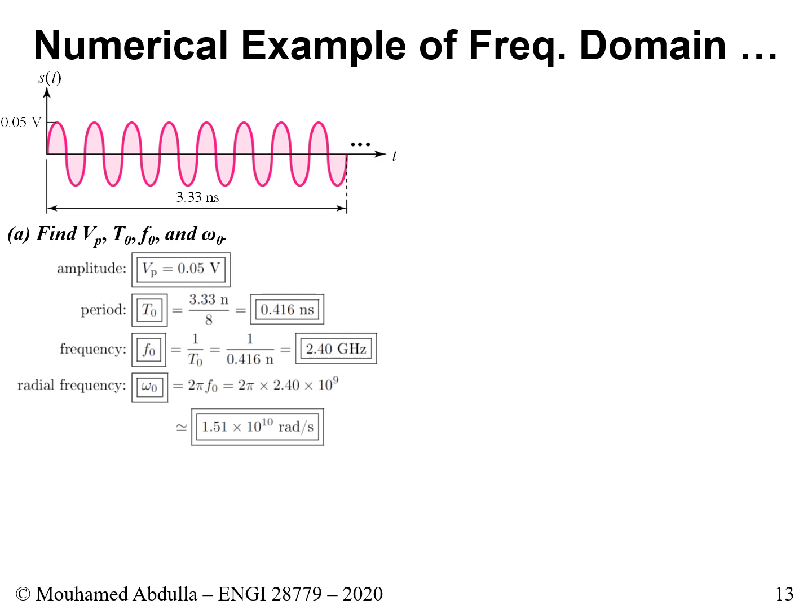This is what we get, okay? So as we said, the peak voltage is 0.05. It's here. It's also minus 0.05. The period is this entire thing, 3.33 nano. Nano is 10 to the minus 9. I hope you know your engineering notation. This is back to electrical fundamentals. You've probably taken this course with me the first semester.